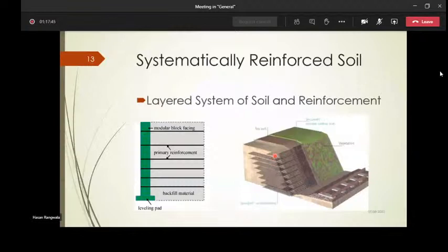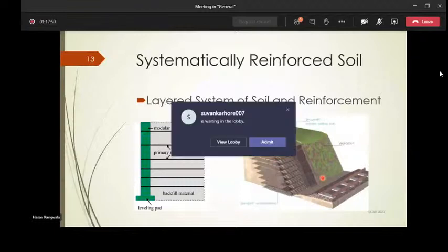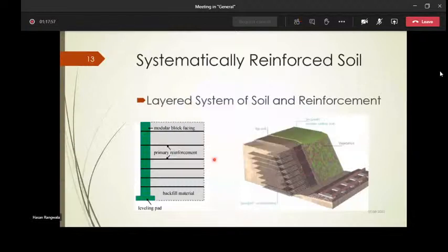So, if I have to make another railway track and I have to make the extension, then because of this I would be going for a steep slope, or I may have to go for a vertical slope. Say, I may have to go for a vertical wall. In that case, what I require is that this soil is to be strengthened, and this improved soil requires some element which has to be added. Okay, this is called reinforcement.